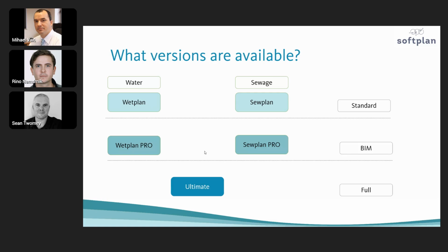You can show multiple terrains and multiple pipelines, and you can parametrically design trenches for multiple pipelines. So if you have 2 or 3 or any amount of pipes going in the same trench, you can design that, and then you can also run the excavation calculation report and get all the quantities of the excavation and all the backfill layers for that complex multi-pipe trench.